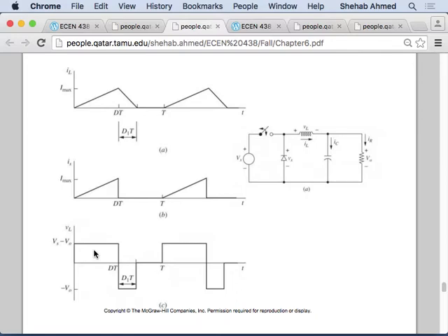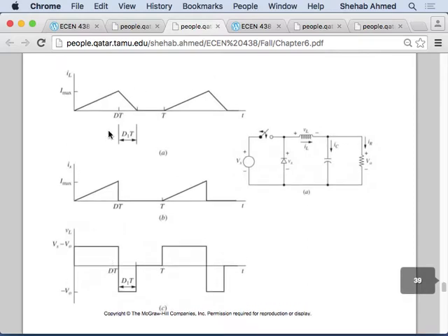If you want to operate in continuous mode as much as possible, you will be decreasing that as much as possible. If you're going to live with a bigger delta I because this is what's practical to build a power supply that's operating mostly under load, then it's okay. Keep delta I a little larger and it's fine. You save on the size of the inductor and the cost of that. So it's a design consideration. But the sizing does not change. It's the area under the curve divided by the delta I spec. Any questions on this?